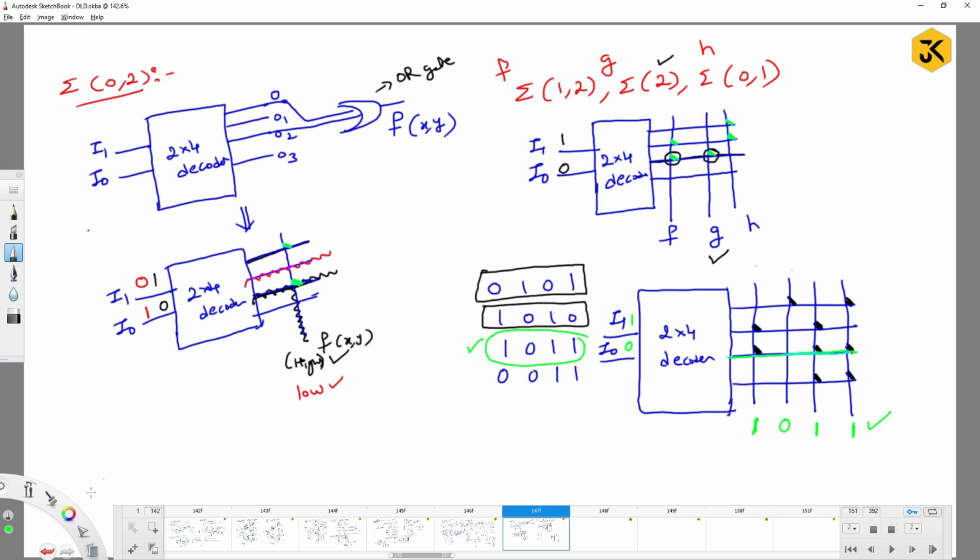Here, another advantage of the decoder is that it can be used to represent a ROM. If you would like to store certain data, we can store it, and whenever we request it by passing certain data, for example, if I pass 10 as input, I get the respective 1011 as output. This is the storage mechanism. So where we store something, I can call it a ROM mechanism, read only memory, right? For example, if I need to get the data 0011, what data can I pass here? I can pass simply 11.